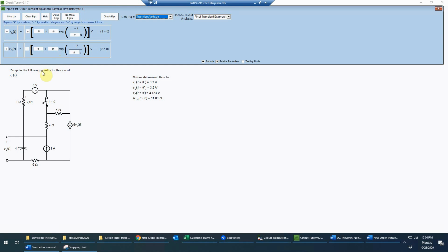And to fill in the blanks here, well, we think about what happens at t equals infinity, for example, because we know that VC at t equals infinity is this value. Well, at infinity, we have e to the negative infinity, and that's going to be 1 over e to the plus infinity, or 1 over infinity, or just 0. So this term goes away, basically, at infinity, and so that value will simply be the constant value that, of course, never changes by definition in time.